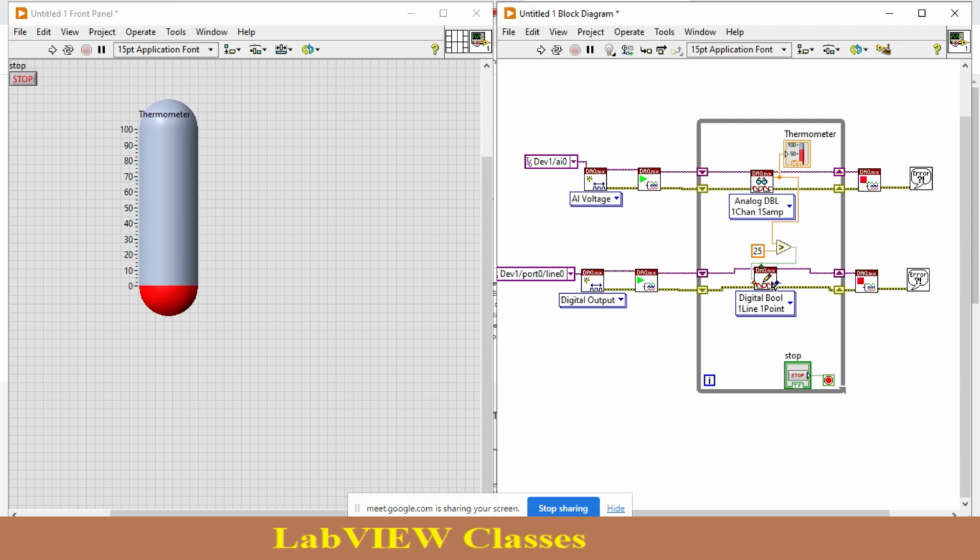Okay, so in this case it will generate a signal for this relay automatically, according to my condition, when the temperature goes over 25 degrees Celsius. It will generate a true signal from here, and this true signal goes to the DAC card, and the DAC card will generate a signal for this relay, and this relay turns on your AC in this case. Using this way you can generate any signal for your chamber.